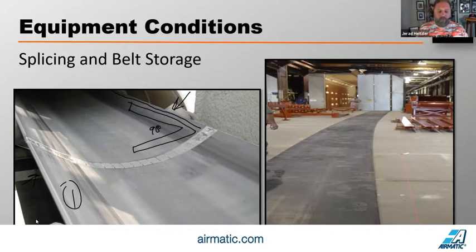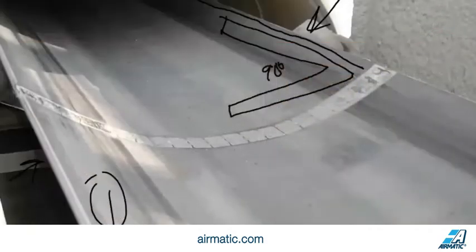If you go to, say, a tail pulley, and you watch that belt, watch that belt, watch that belt, and then all of a sudden that splice comes through, and you see that belt jump very quickly to one side and jump back. That's a crooked splice. That happens because they've squared off this edge of the belt.